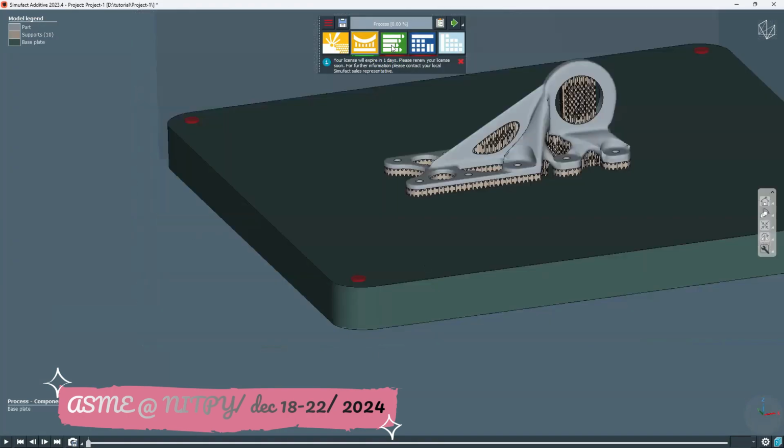Sometimes what will happen is when we are leaving a gap of 5 mm, if we give a distance more than 5 mm, it means that you will be cutting the part also actually. That should not happen. So the cutting should be within the gap, which is between the part and the base plate actually. That should be taken care of.